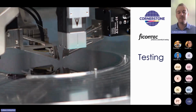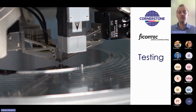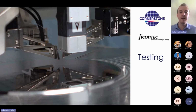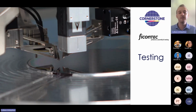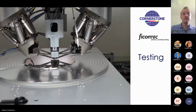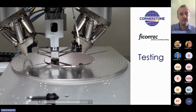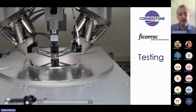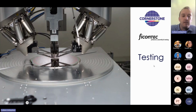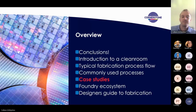Okay, once that's all done, we've finished our wafer. Clearly, we want to test it. And within Southampton, we have a very nice wafer scale test capability. This video is showing an optical test. If you can just make out a fiber coming in from the left-hand side, I'm not sure if you can see my cursor, this is an optical fiber input and output. This is an automated system that lets us do hundreds of measurements per day, so we can really get nice data showing different tolerances across the wafer.